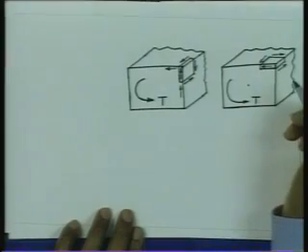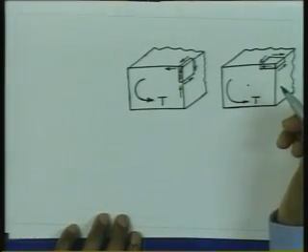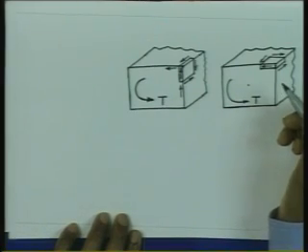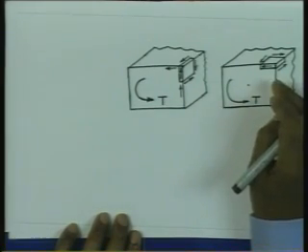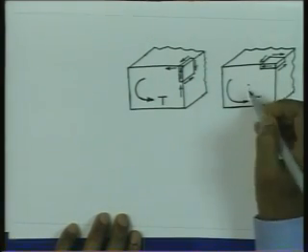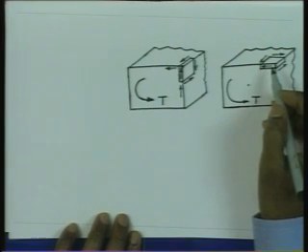So, corner stresses: the same type of argument can also be considered for the triangular cross section. We will find that for that matter any corner is going to be free of any shear stress in a torsion problem. So, note that the stress at the furthest point, which is the corner, is 0. In the case of the circular shaft, we have found that the stress is going to be maximum at the furthest point, but in such a cross section it is different.